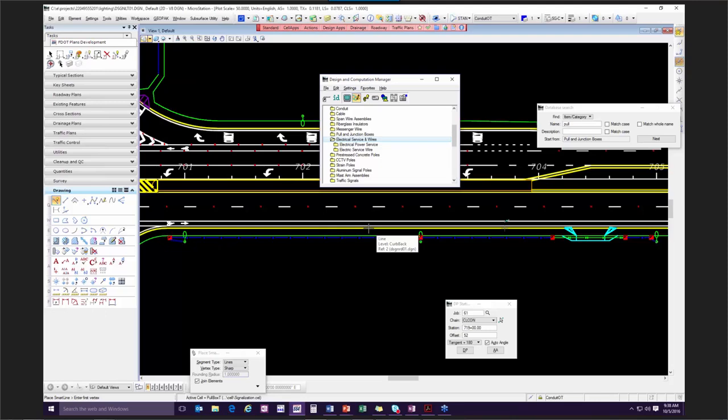It's almost easier for you to not draw the conductor in there, you just need to label that that conduit has that conductor and then do the math. If I've got 200 foot of conduit running from this pole box to this pole box, it's 200 feet times 9, and then you have to add for however many are coming out an extra 8 feet.